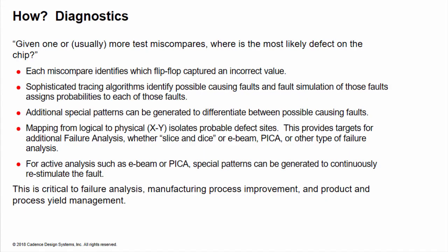It can be very valuable to monitor the types of defects that are occurring. This can identify weaknesses in the design of the technology cells and act as the ultimate monitor of the technology process and manufacturing line. If the defects are dominated by one type of defect, for instance, it is probable that the process can be adjusted to eliminate most of that defect. This is how the yield of a technology process is improved over time, holding down the cost of chips and enabling Moore's law, as well as helping us sort out good chips versus bad chips.